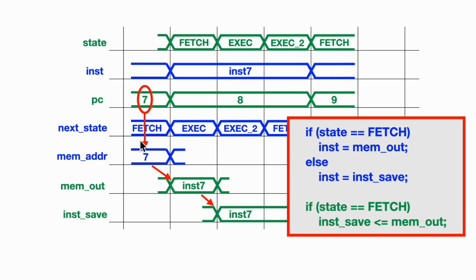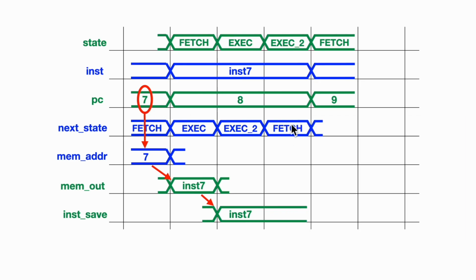We also see that we have to compute on the previous instruction, or I should say the last state of the previous instruction, what to feed into the memory. And so typically that is the program counter, but for branch and call instructions where there's a change in the flow of instructions, we might be feeding something different into the memory.